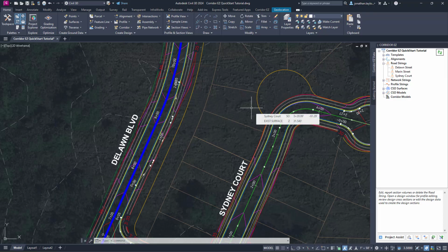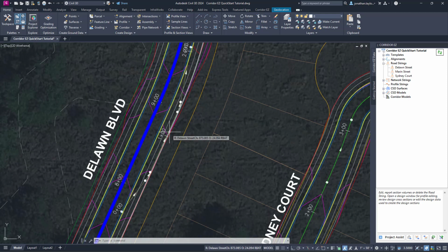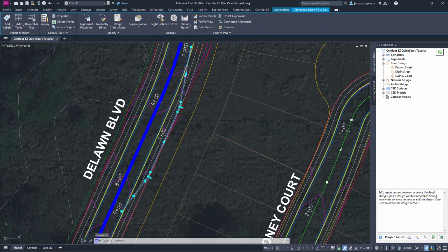We're now going to look at how the design data form allows us to apply something called design variations. And design variations will allow us to override the cross-section design that is being applied, in this case to Devon Boulevard. What we're going to do is widen Devon Boulevard by getting it to use this Civil 3D alignment, meaning that the right-hand side of the design will be widened out to it.